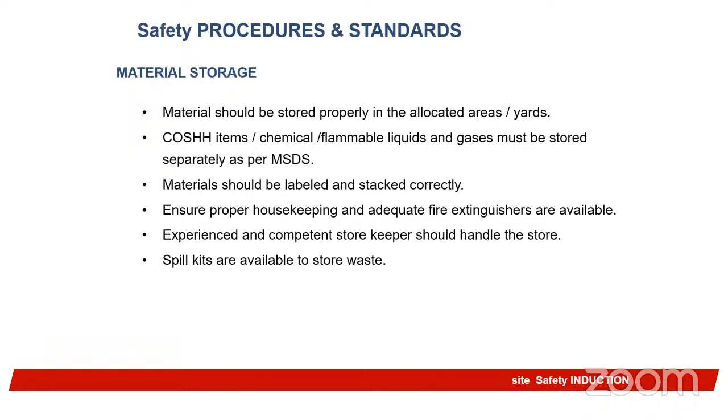Materials should be stacked correctly and properly. Material should be labeled. Someone should not be carrying a particular substance or chemical in a container without an average person walking around knowing what is in that chemical. Maybe it's petrol, maybe it's vinegar, whatever it is that is inside that container, it should be properly labeled. Ensure proper housekeeping at all times and your fire extinguishers are always available at the storage point, especially when you are storing flammable materials.